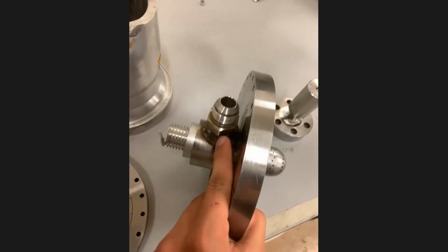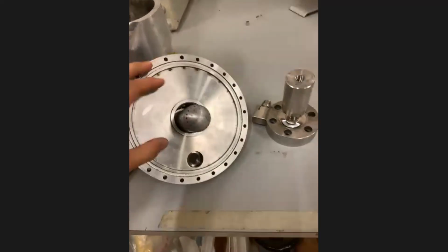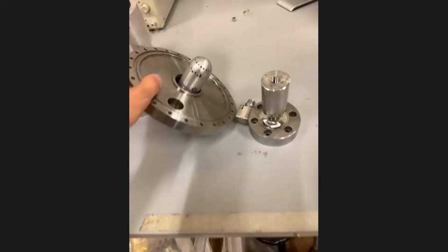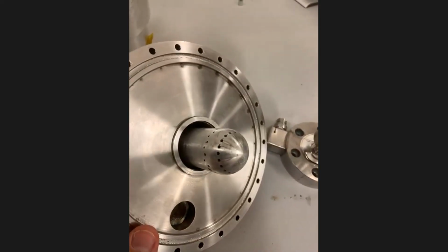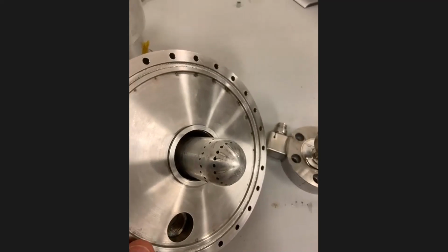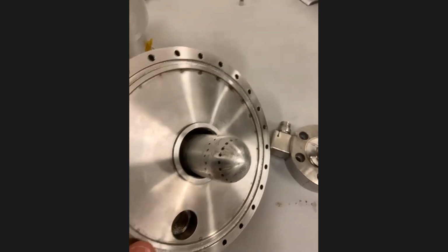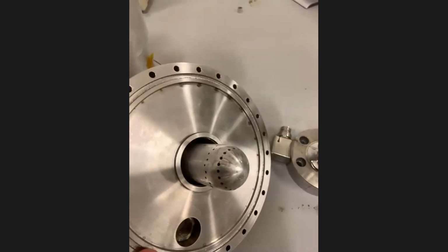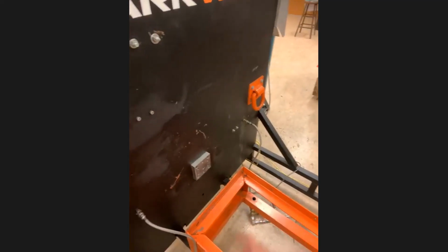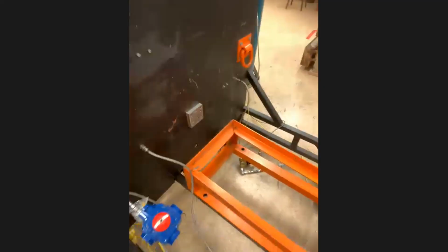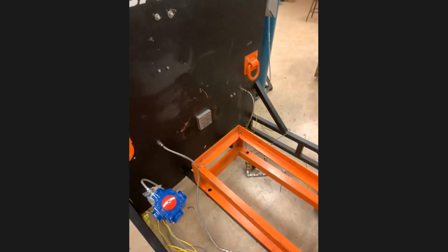Fuel comes in one side, liquid oxygen goes down the middle. And so the fuel comes out as a ring around the pintle, and then these little holes right here are how we inject liquid oxygen in, and that creates turbulent flow inside the chamber and allows us to get good mixing. And so once those are all assembled together, they come over here and sit on our test stand like this. The load cell goes right there, and it pushes all the force into the load cell.